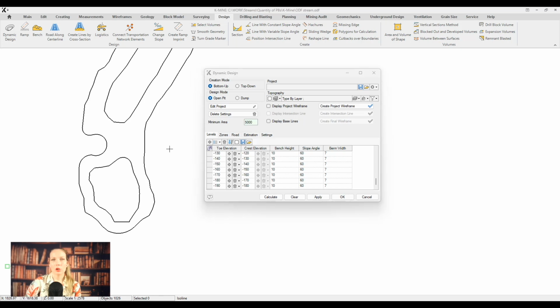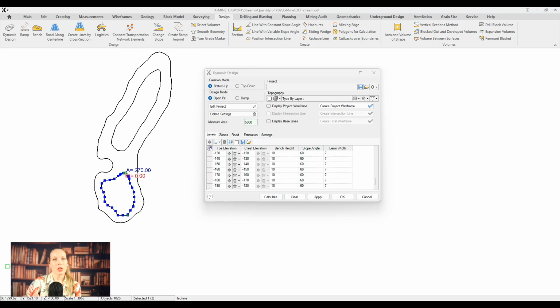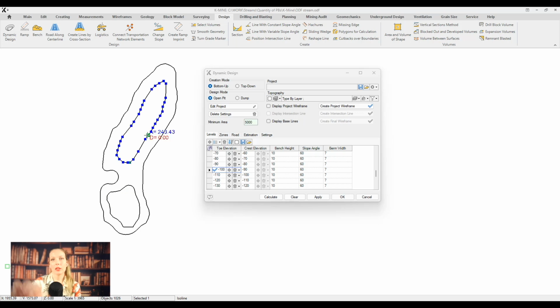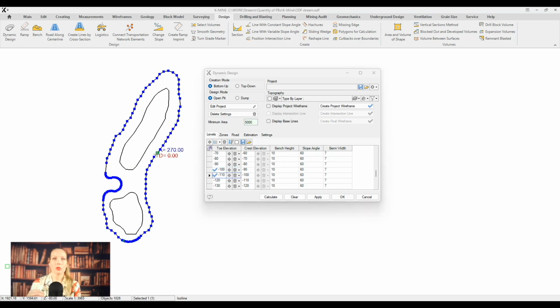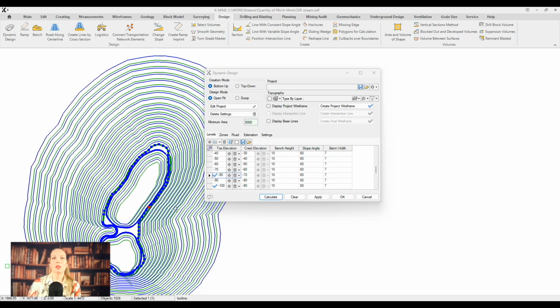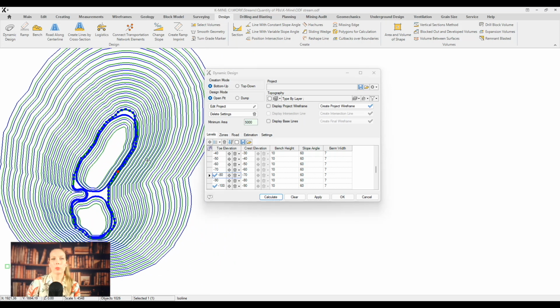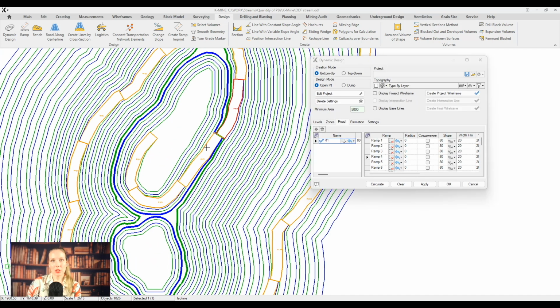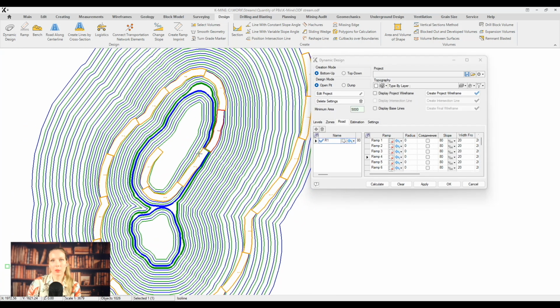We make a list of levels, which is super easy with automatic filling. And you just need to know your pit specifications. Then we decide which baselines belong to which level. If a line isn't at its assigned level, we project it onto that level. Then we start building the edges. We add one row, then another, turns, connections, and so on to make sure every part of the pit is accessible. Each section of the project must be mineable.